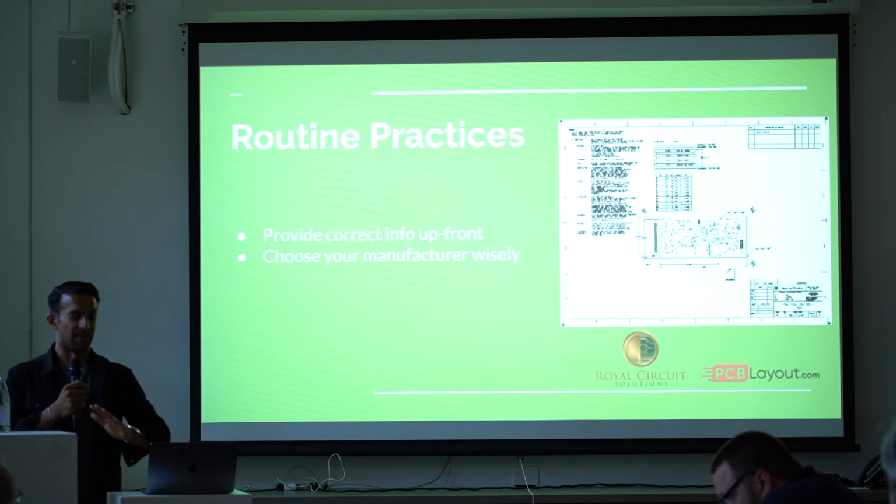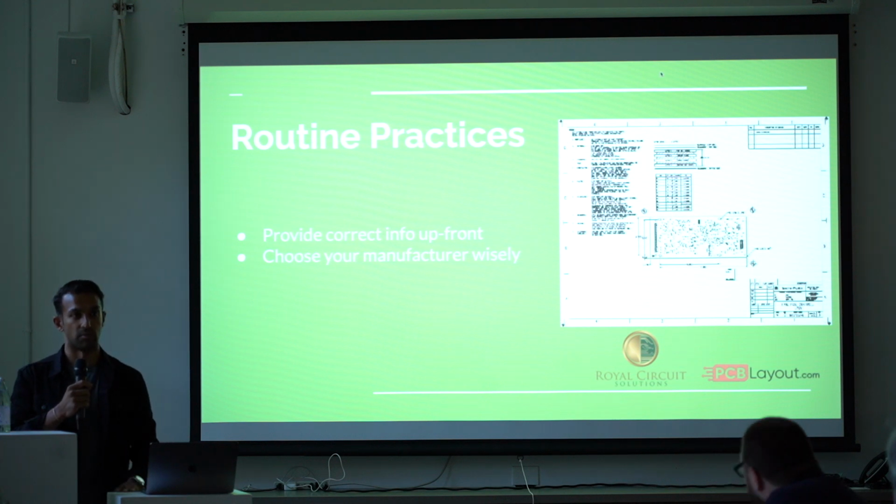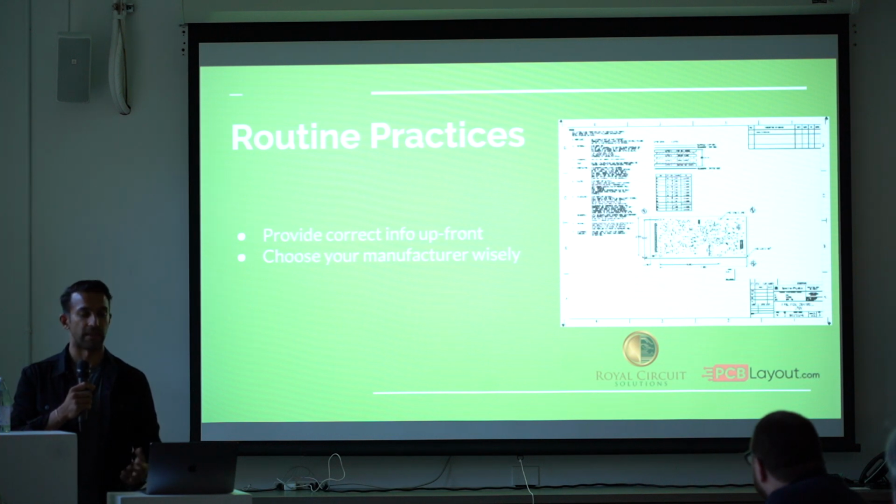So at the basic level, routine practices, this is a fab note. Have you ever sent in a fab note when you sent your boards to be manufactured? A few. Depending on the complexity of the board, but generally it's a PDF note. This is a standard fab note. When I was at Tesla, this was what the fab note looked like.